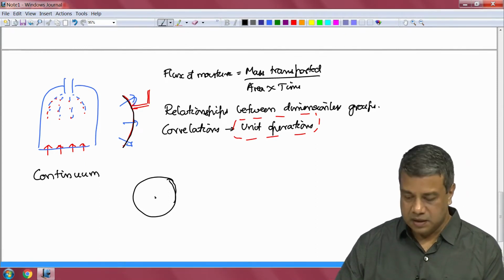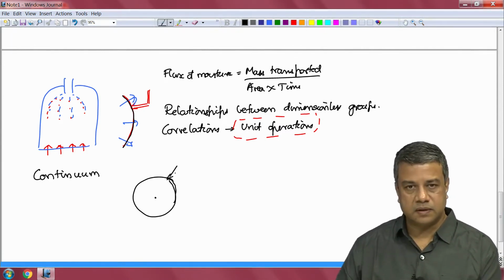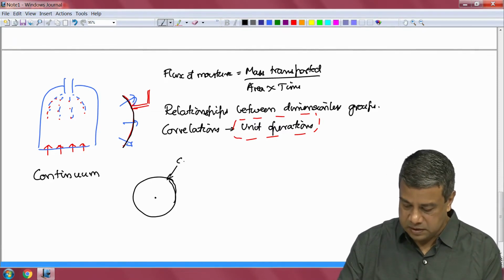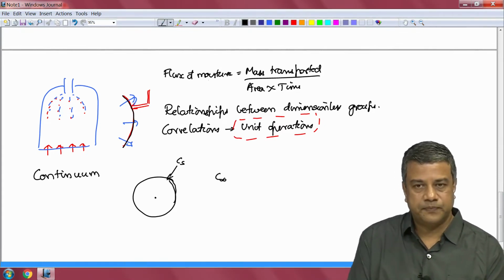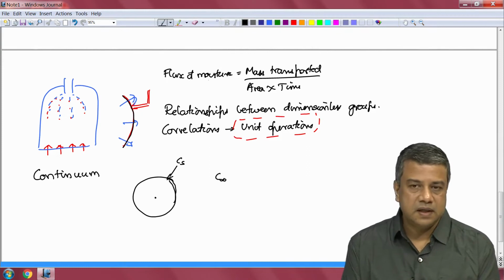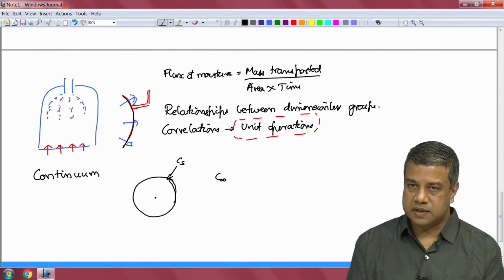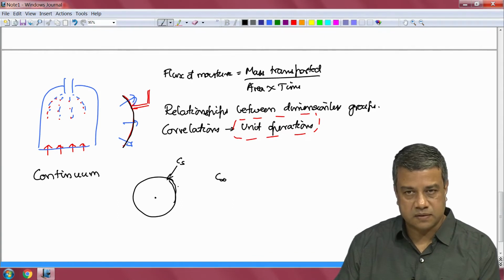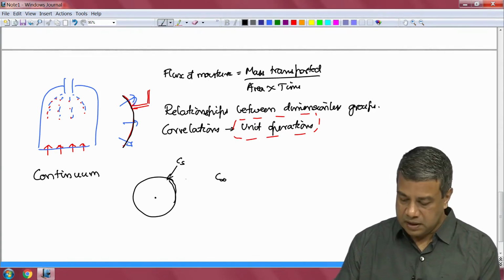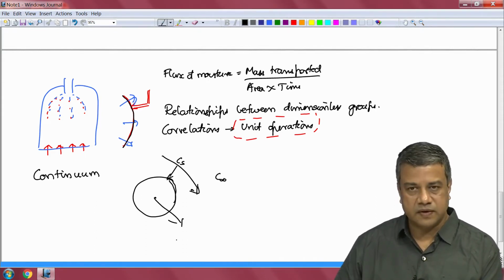and you know what is the saturation humidity at the surface, or the concentration of moisture at the surface, and you know the concentration of moisture in the ambient far away from the surface. So, you can solve the concentration diffusion equation. It contains different components. One is the mass diffusion from the surface due to the fluctuating velocity of the molecules, and the other is the convection around the surface, because this droplet is moving relative to the fluid.